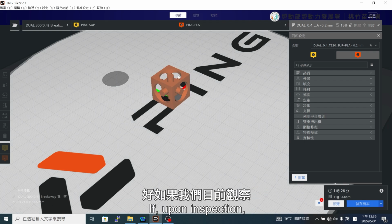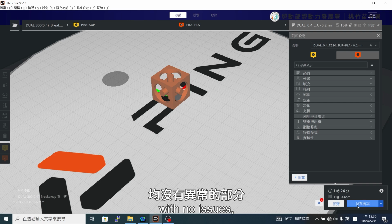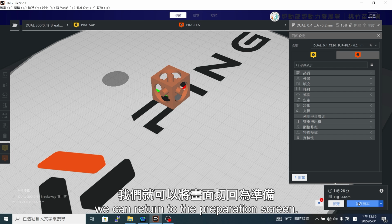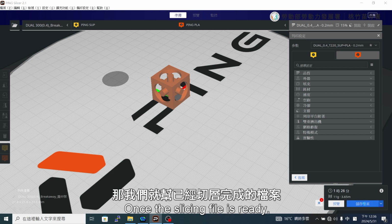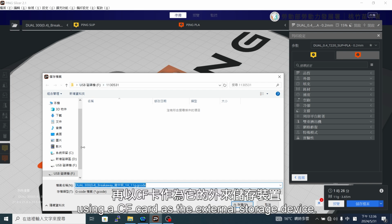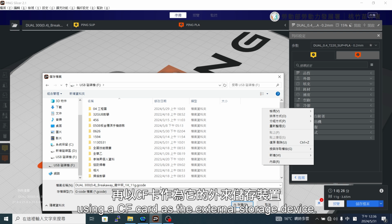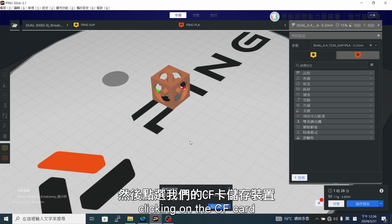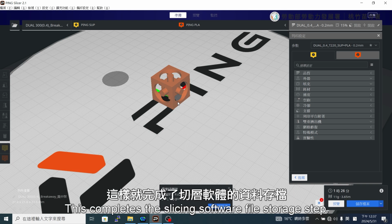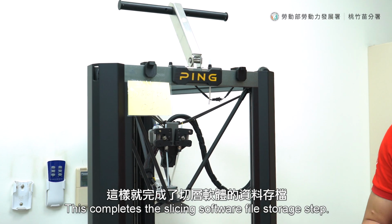If upon inspection the model and support material are in good shape with no issues, we can return to the preparation screen. Once the slicing file is ready, we save it using a CF card as the external storage device. We proceed to save the file, click on the CF card as the storage device, and then it completes saving the slicing software file.